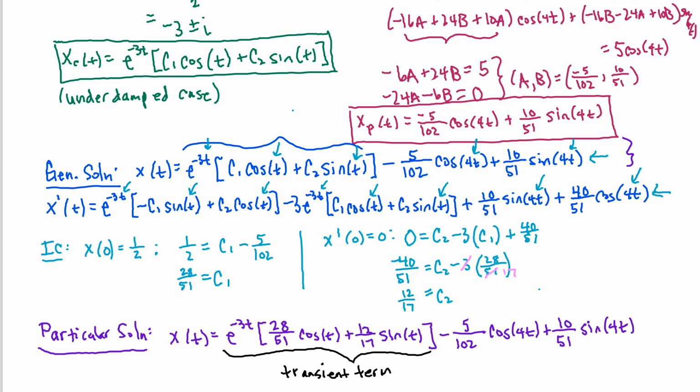The mass will begin oscillating according to the natural physics of the spring. We can recognize that omega naught here is 1, and the mass will oscillate between two exponential envelopes and eventually settle down to equilibrium. While this is happening, it is still being affected by the external forcing function. But over a long period of time, as my transient term goes away, levels out at 0, this becomes our steady state solution. So the external forcing function will take over in regulating the oscillation of that mass.